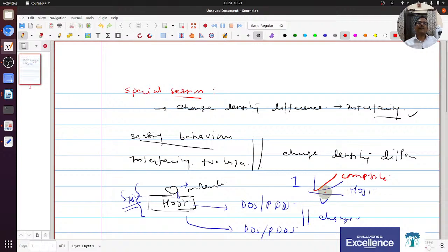If there is some change in the curve in negative and positive bias, then we can say yes, it has sensing behavior. In some papers, especially for sensors, a gas molecule or biomolecule is attached to, connected with, or interacting with the host material, and that host material may be nanoribbons, nanotubes, or whatever nanomaterials you want to use, also in the form of polymers.